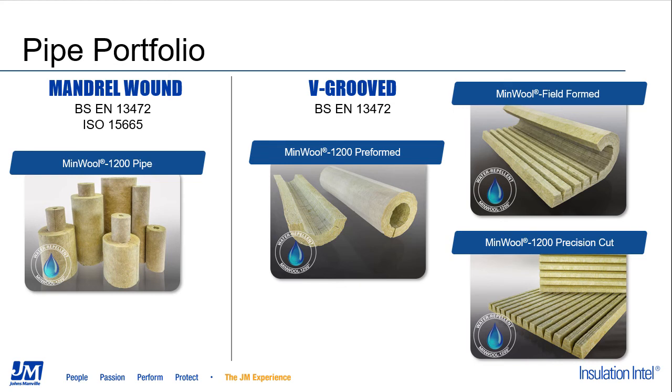In field formed, where it does ship to you flat with adhesive in the grooves, and the installer would curl it around the pipe during installation, or in what's known as precision cut, which is the same as field formed, but just does not have any adhesive in the grooves and again ships flat.